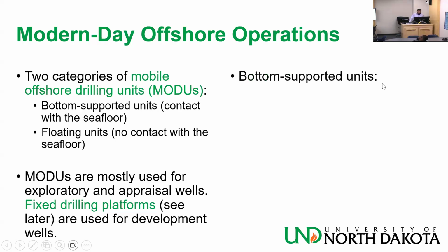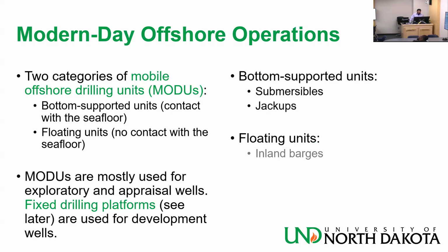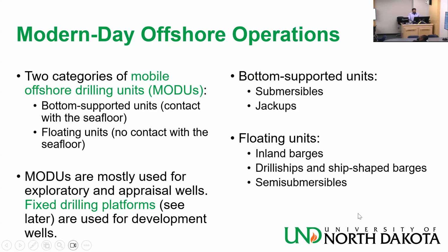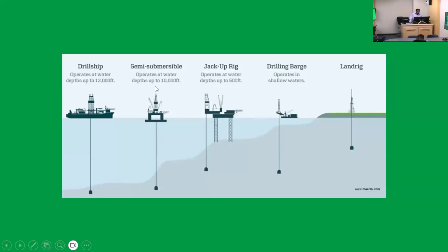Now, bottom supported units, several categories: submersibles, jack-ups, floating units. You have inland barges. That's the ones they use in Louisiana. Drill ships and ship-shaped barges, semi-submersibles. And this is how it looks like, this picture schematic from Maersk. You have an onshore rig on the right, and then you have a barge. Barge has a flat bottom. Okay, that's a barge. It's the shallow, that's the Louisiana stuff.